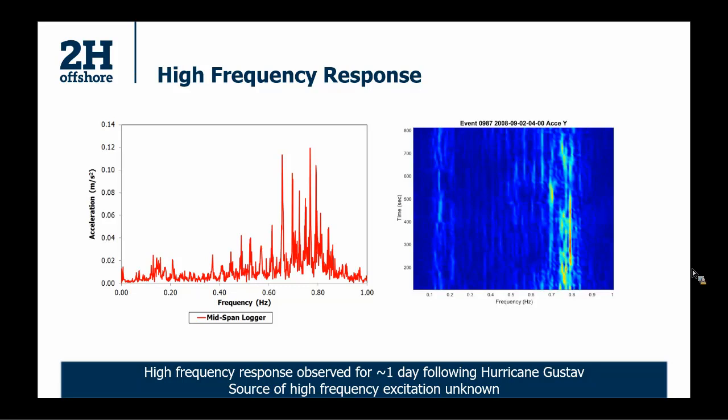And on the right side, I'm showing you the so-called waterfall plot, which is just a time varying FFT, basically multiple frequency plots stitched together, the frequency plot being on the left. And it is showing the same response, basically, almost a very consistent response at 0.8 hertz.